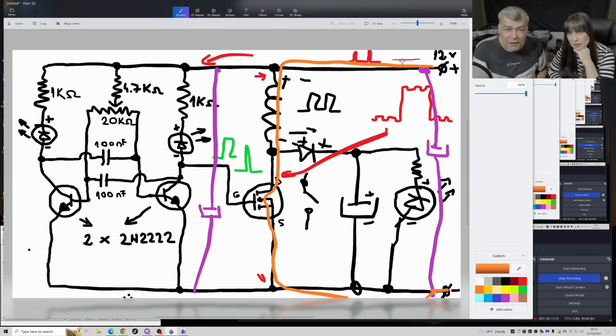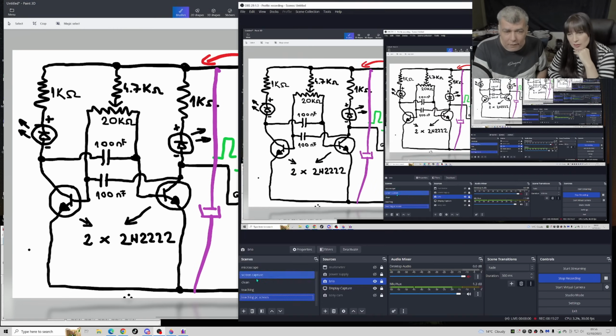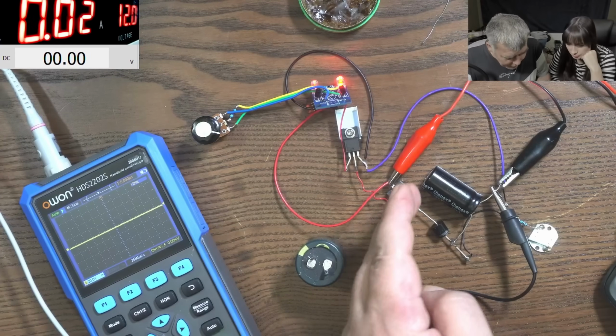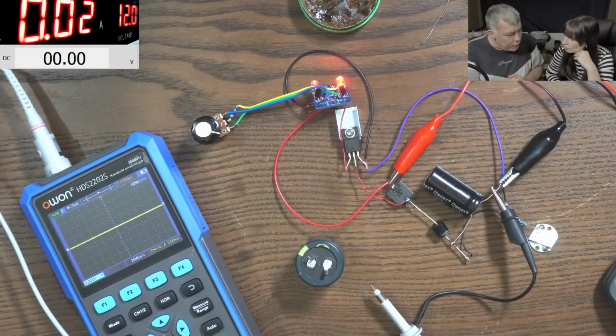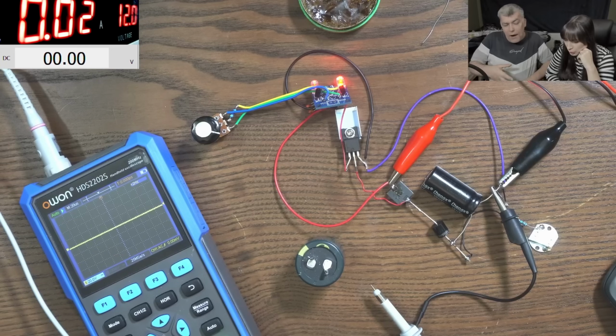Now you have to understand. You see this part from here to here? What is this? It's a wire, right? Like the ground wire. A wire is never ever just a wire when we are speaking about switching or RF. Actually, here it's kind of RF. RF is radio frequency. But it's not that high, so it's high frequency switching.